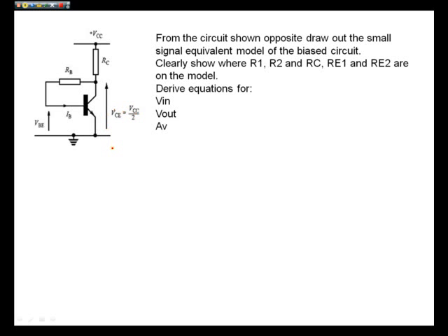And we have another quick screen cam from Seminar 5. What we're looking at here is a small signal equivalent model for this feedback bias circuit. Now inside this design we have a slight complexity in the fact that the collector loads the base with its value of current. So that means in effect that we've got some sort of feedback. So let's draw out the small signal equivalent model for this design and let's see what we get.